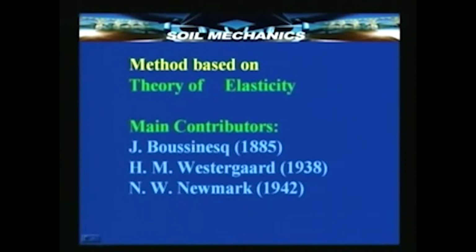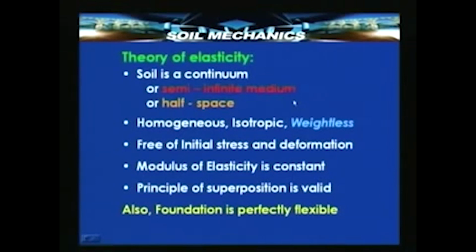We shall be seeing today Boussinesq's theory of stress distribution, which is essentially the application of the principles of theory of elasticity to the problem of stress distribution below a foundation resting on soil. Let us first see what this theory of elasticity is all about before we see how it has been used by Boussinesq in computation of stresses.